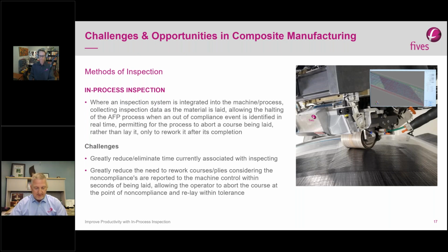So imagine a part, 22-foot diameter, 40-foot long fuselage for a commercial aircraft, a 45-degree ply where you helical wind the material, and at the very beginning of the course, the toes are all short, or 1 or 2 of the toes are short, it doesn't matter.